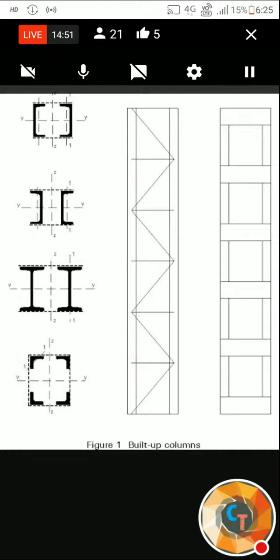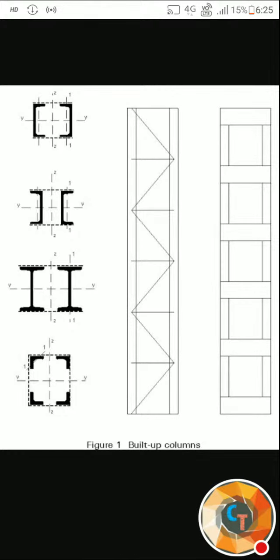Okay, thank you. This much will be today's discussion on lacing and batten connection. Lacing and batten connections all come under built-up columns. Yesterday also, we were discussing built-up columns itself. Built-up means I sections with plates, that is also a built-up column, and the members along with the angles or plates that we use, that is lacing and batten connection. These all come under built-up, which are not rolled sections; we have made built-up sections and later used them, right?